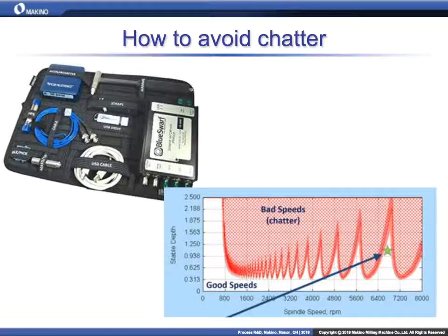So the faster you can go, typically you can enter into these bigger and bigger sections of the white stability lobe diagram, where you can not only get rid of chatter, but maximize your material. You're not suffering. There's very few instances in life where there's no trade-offs. But with this, going at a higher spindle speed allows you to feed faster. Going at a higher spindle speed allows you to cut more in your axial depth of cut. So it's a win-win for manufacturers. Big gains to be had in aluminum for sure.